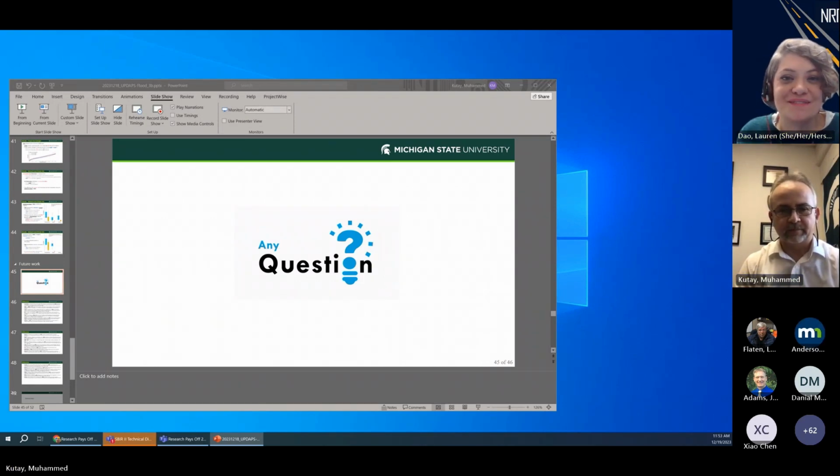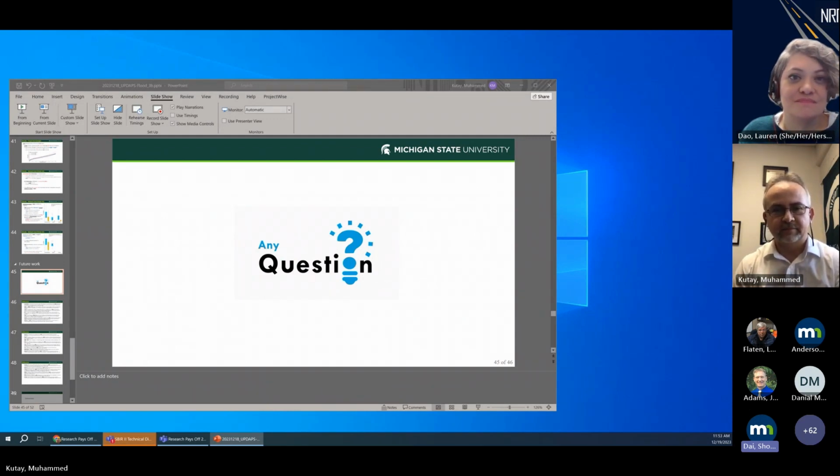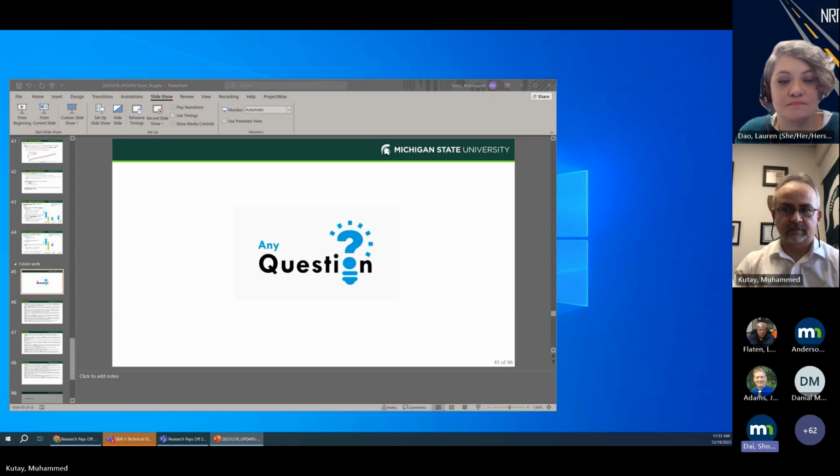Okay. Yeah, next presentation. Thank you for the presentation. This is Xiongtao Dai from Minda. I think you talked about the flooding decreasing the resilient modulus, which is for base materials. Yeah, I agree with that. But another aspect is not only the stiffness reduced, but also the strength is reduced. So sometimes, given a weak strength base, under one heavy traffic load, the whole pavement can fail.